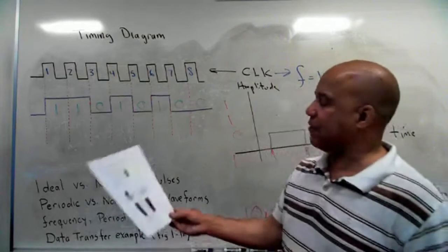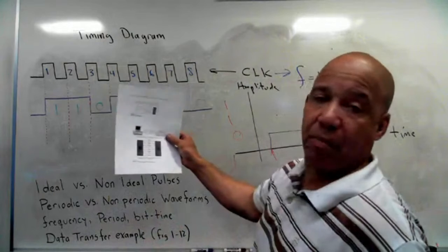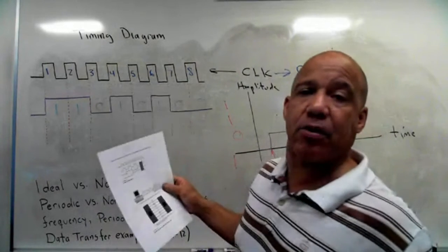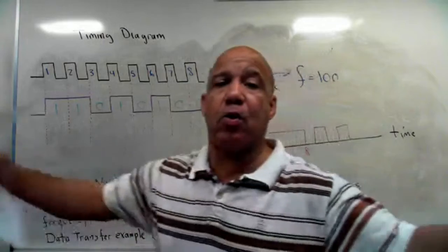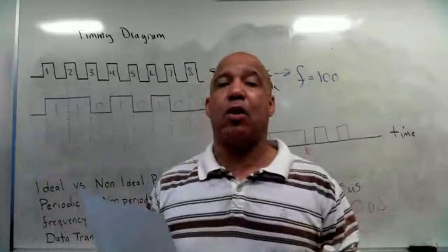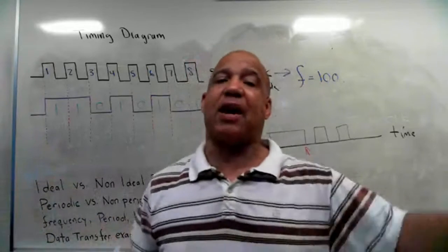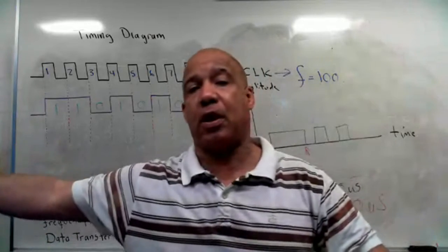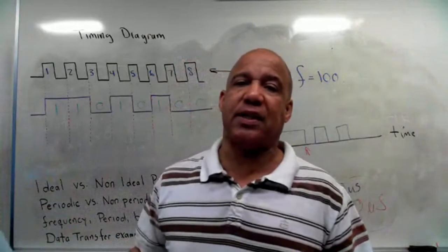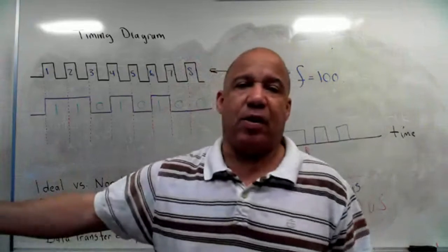Well, in this diagram, at the very bottom, they show a microprocessor talking to memory, or maybe memory talking to a microprocessor. And typically, inside of your cell phone or computer, when those devices inside are communicating between each other, they do so in a parallel fashion. When you transfer information outside, like from a digital device to a printer, typically they do that in a serial fashion. And the reason is, serial is way less expensive, but it's slow.